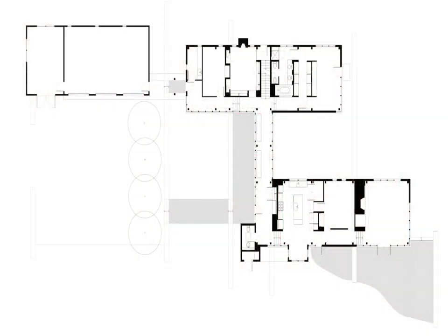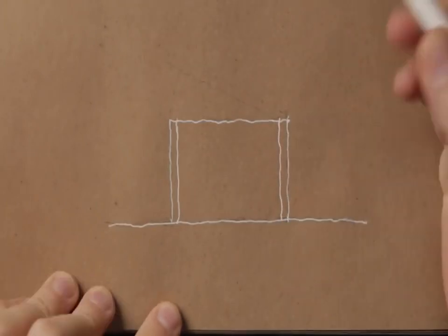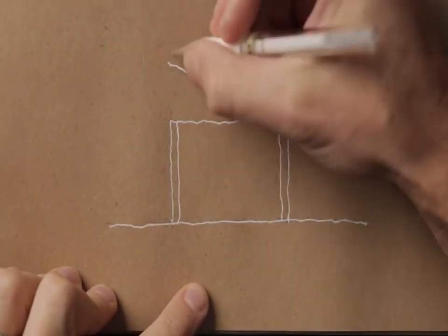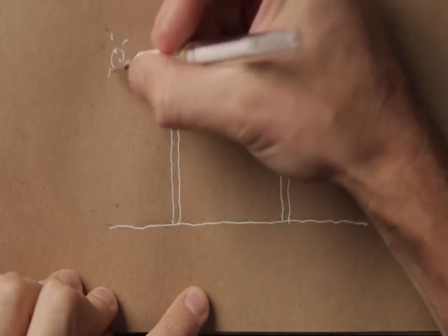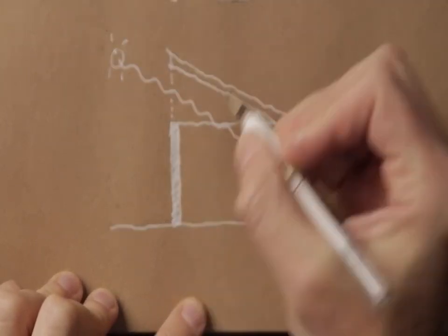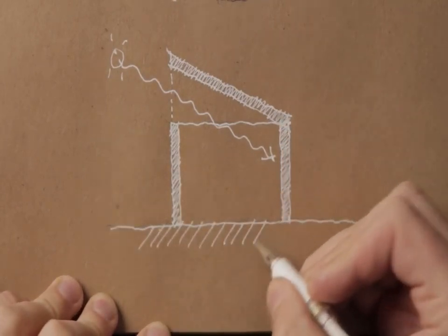The plan is laid out as 3 linear bars, each stepping down with the topography toward the water. An initial approach might be to simply extrude the bar and put a flat roof on it, but this is less dynamic. It doesn't really react to the solar exposure in any specific way. But by picking up the southern eave of the roof like this and adding a glazed clerestory in the void, this became a really efficient device for letting in sunlight on the southern exposure. The higher you can locate a window on a wall, the deeper it will admit daylight into the interior.